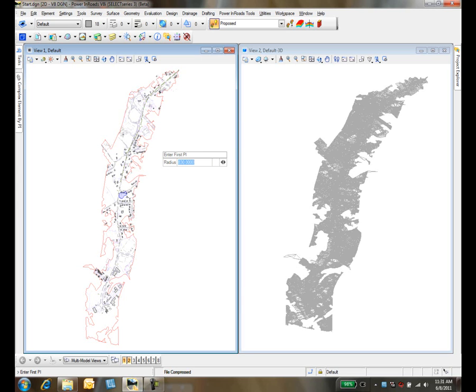So we're going to start out here, and we'll just start with, let's say, a radius of 450. Again, I'm just going to eyeball something through here for the interest of time. So we'll just start somewhere down in here. We'll move up into this area here with a radius of 450. Let's flatten that out a little bit, say to a radius of about 830. Okay. Go a little bit flatter here to a radius of, again, about 1170. Okay. Come back even a little bit flatter with a radius of about 1500.